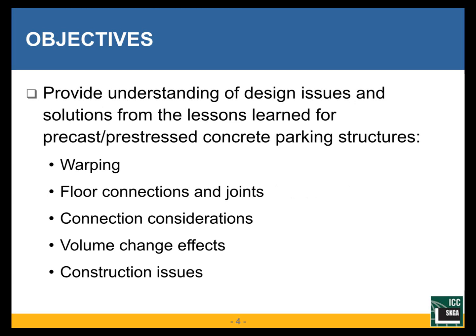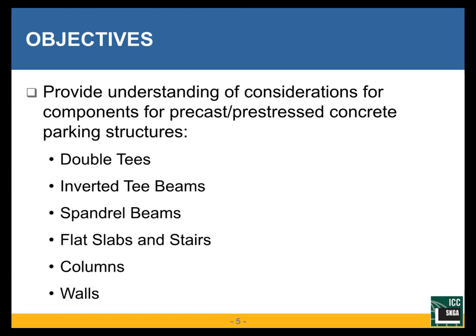Finally, we will look at design issues and solutions from lessons learned in precast parking garages, including warping floors, floor connections and joints, some other connection considerations, volume change effects, and construction issues. Then we will do a little bit of covering of some of the components that are used in precast prestressed concrete parking garages: double T's, inverted T-beam, spandrel beams, flat slabs and stairs, columns and walls. All of this is an overview to be able to, in one session, put together the basic considerations